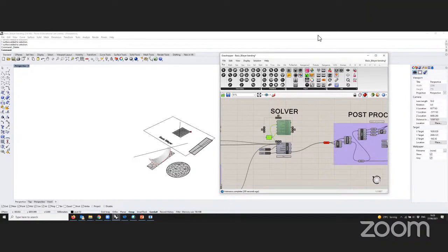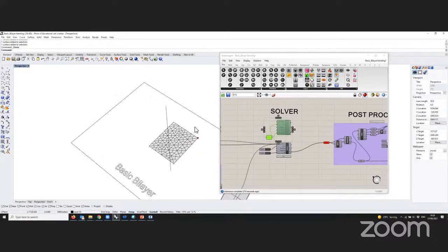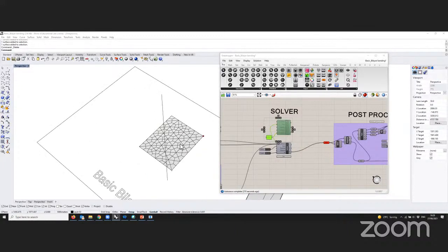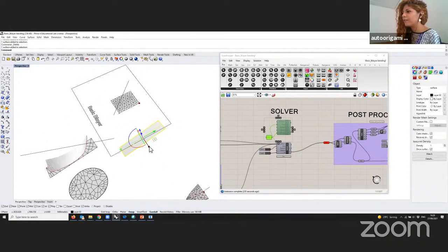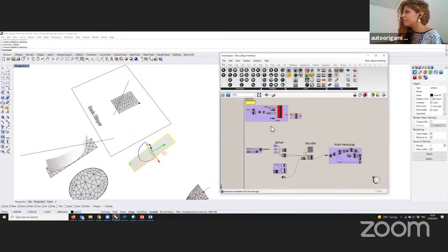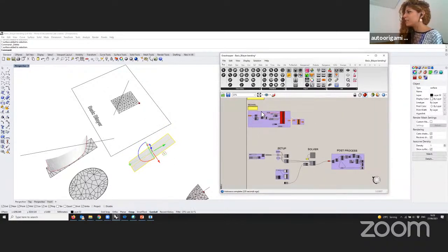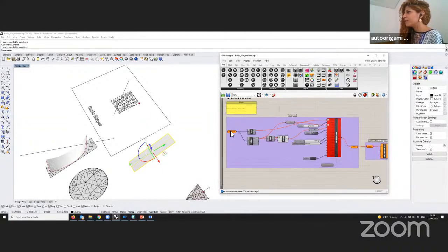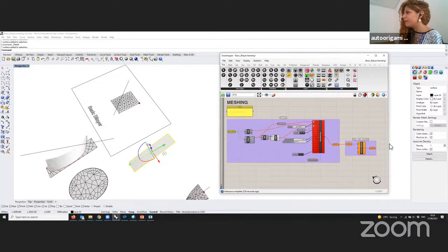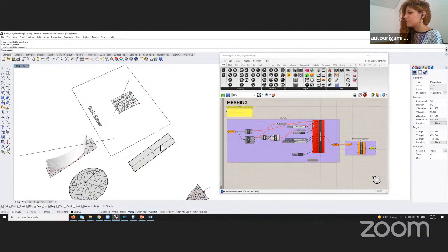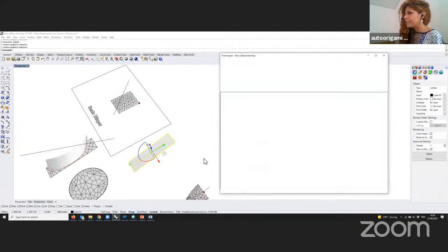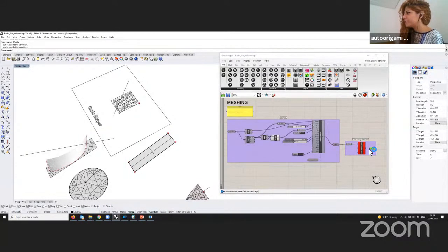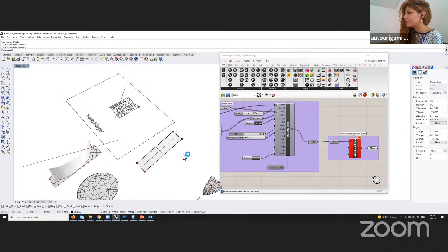Hi, would you mind running over how you got the pattern on the plane surface? The step when you drew the plane and then... Oh, yes. That was here. So you have the plane. This is what we have here on top, on meshing. You go here, you need to reference an input brep, and at the end you get a mesh. So you draw the brep in Rhino, right click, set one brep, reference it, and here at the end comes the mesh.